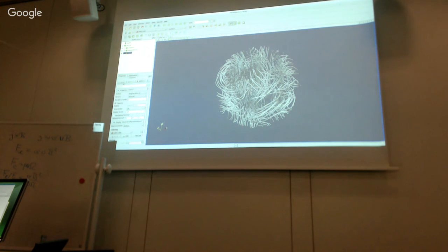want to highlight is the region where you have most of the induction. And ParaView offers a very nice feature here. It can vary the thickness of your field lines by some scalar. And that's what we're gonna do here. So vary radius here, we turn it to on and we set by scalar. So which means that the size of my field line is gonna vary by scalar. And I have to choose which scalar I want.